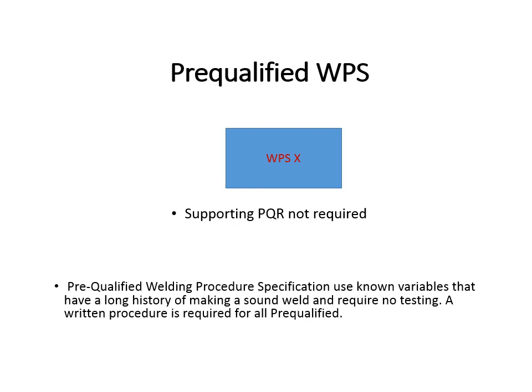And AWS allows the use of pre-qualified because there's been so many welds made over the years with certain low carbon steels, and let's say E7018 or E6010, that if you follow these rules, you're probably not going to make a mistake or have something bad go wrong with the weld that you're making for that particular structural component.